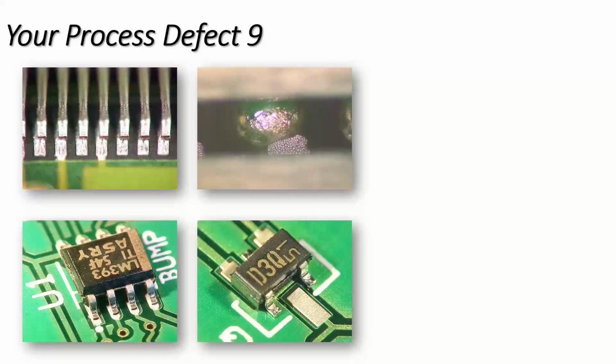So classic example is I was working on a problem with ultra small via holes, capped via holes, and I could do the microsections and show the end result, which is good, but the customer wanted more proof. So we went from a microsection which may cost you £400 to another technique which costs around £5,000. But if you have to have the data to prove the point from a scientific point of view, then it does become a lot more expensive.